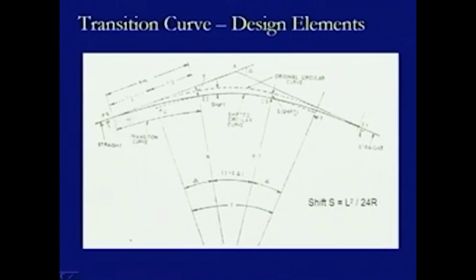So, to provide this connectivity, otherwise if we simply provide the circular curve, it is the circular curve which is starting from somewhere here and ending at this point. Now, because of the properties of this transition curve, we have to displace this circular curve by some distance, and this is the distance by which it is displaced downwards so as to meet at this point, and this is how the connectivity is provided.